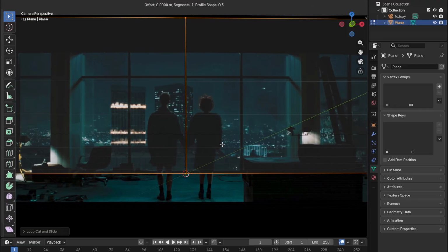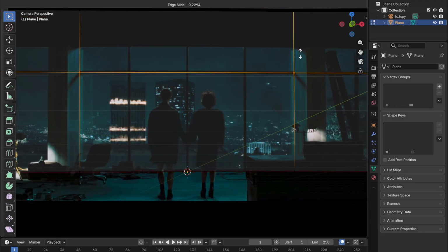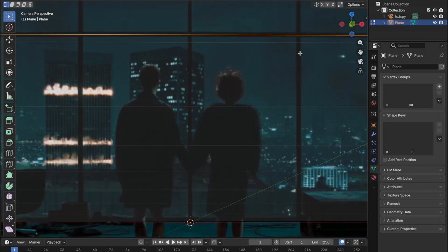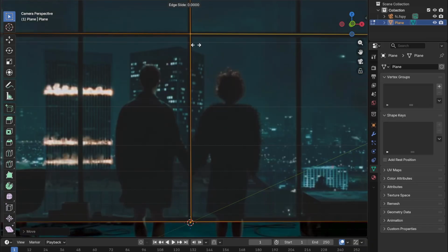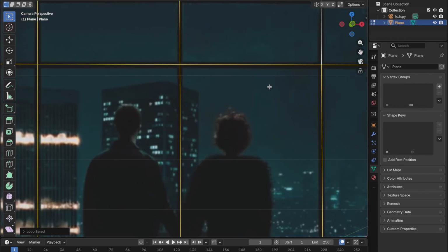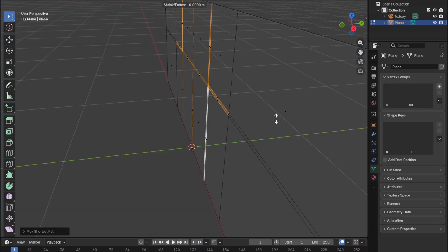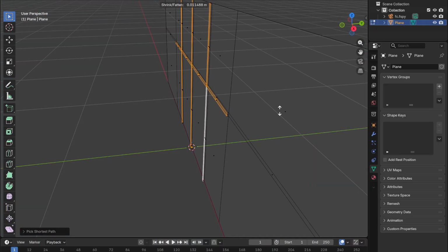We will again define the main central window and add another edge in order to anticipate these metal structures, the metal parts of the window. Using Command B we will outline our metal structures and extrude them along the y-axis forward toward the camera in order to, strictly speaking, replicate the geometry of our window.